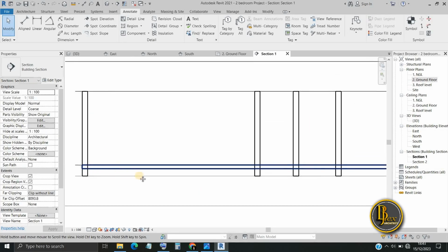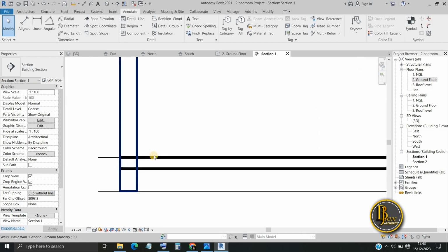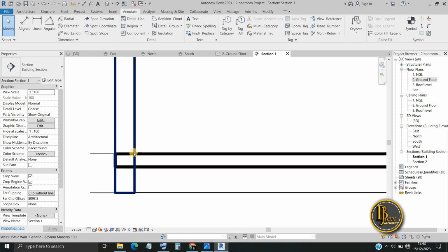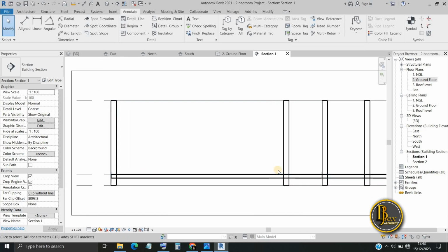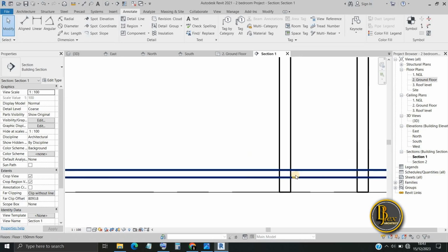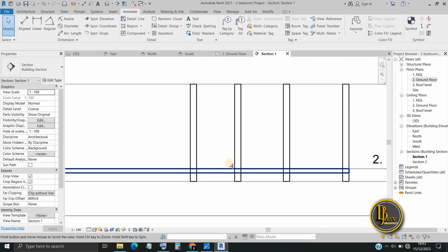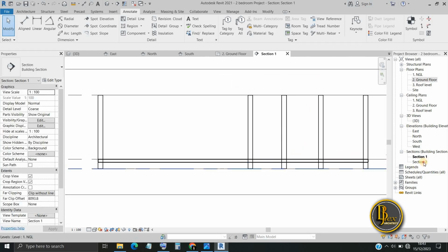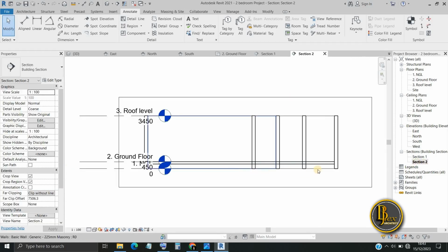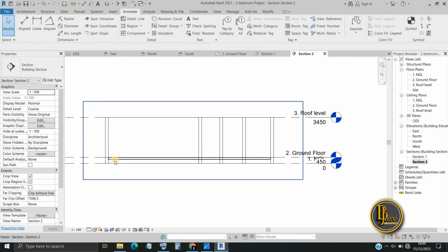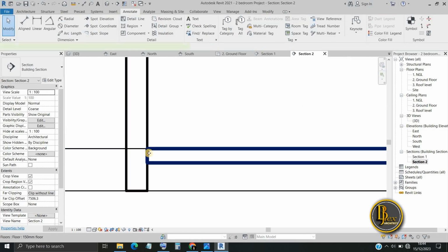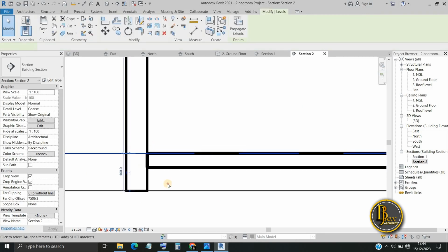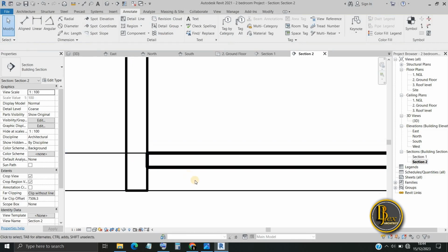This looks almost good on section because the floors are going through the wall, which is the way a section should look. But if you're working on section, you still have to clean up some things. Your section is mostly on detail line, because if you cut section in Revit, it's not going to be looking that nice, so you have to still use detail lines to edit your sections. So this looks better in section in a way, but section also needs extra detail lines. If you look at this particular one, the floor looks like it's floating, it's not going through the wall, but there's a fix to this. You can actually fix this with detail line, which when we are getting to the section area, I'll be showing you how to edit your sections in Revit.